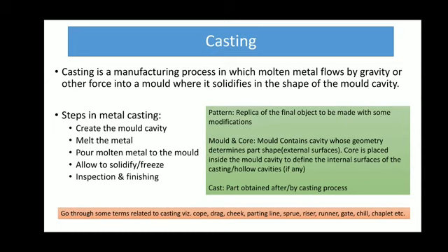And at the end, once the freezing or cooling process is over, depending on what kind of mold we have worked on, whether it was a permanent mold or an expendable mold, that means whether we have to break down the mold or whether the same mold will be reused again and again, based on that we will take out the final product. And last, we will do the inspection on it: whether the desired properties have been achieved, whether the desired dimensions have been achieved, whether there is any fault, crack or other marks, whether the product is acceptable or not.